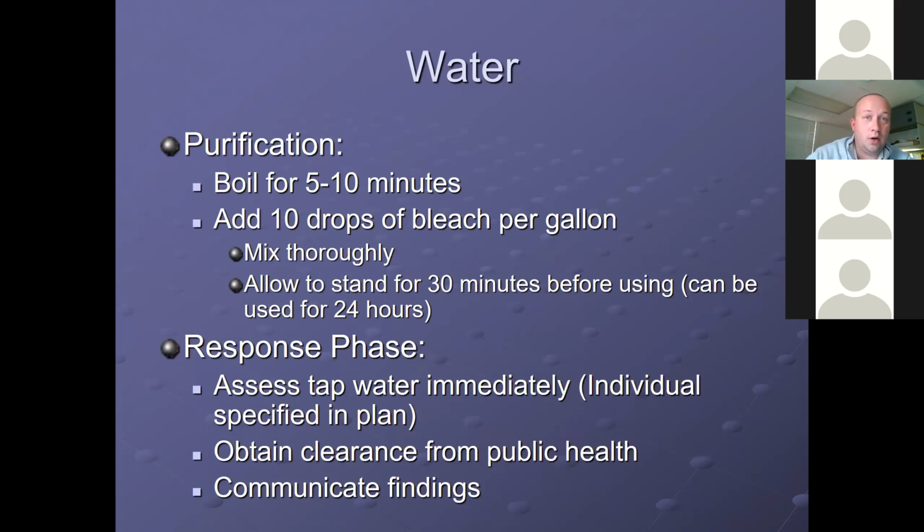By allowing water to continue to course through our building, we did not have to flush our valves. In other words, we kept water flowing through as much as we possibly could. Then once the water built up, it flushed everything out. If you isolate your building and let it run dry, you can have significant issues.